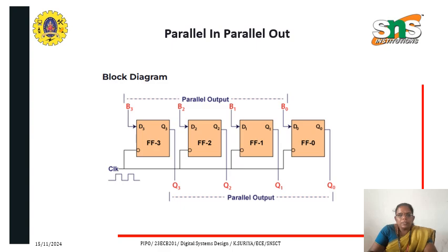Each flip-flop can pass its content sequentially to the following flip-flop to shift the data out. This can be accomplished by providing a clock signal that triggers the shifting operation. When the clock signal is activated, the data in each flip-flop is transferred to the adjacent flip-flop, allowing new data to be loaded into the first flip-flop.